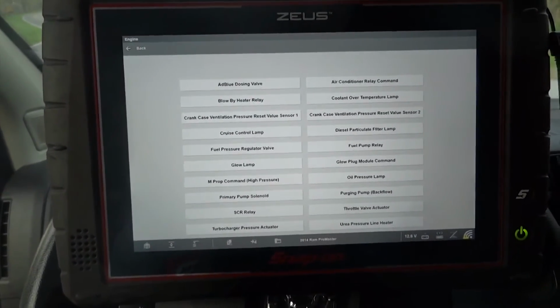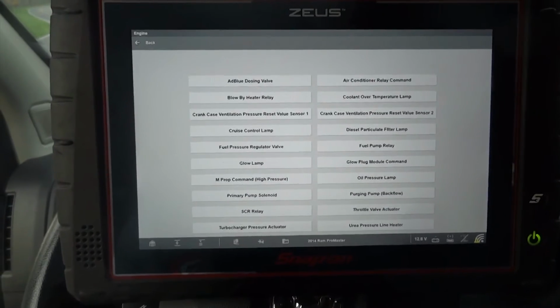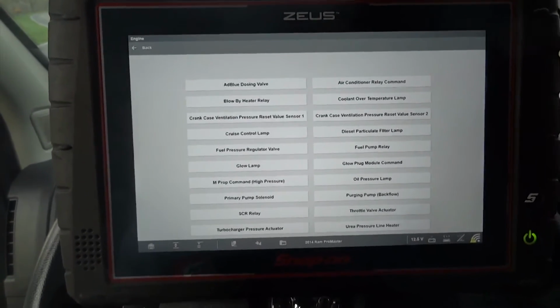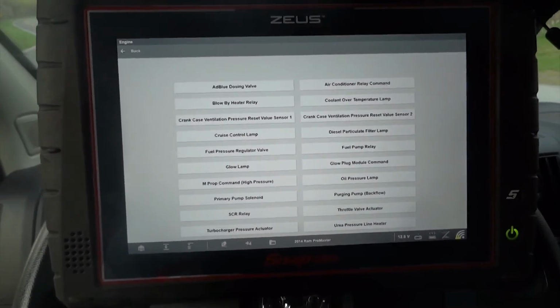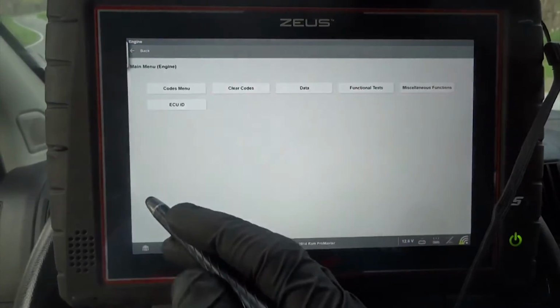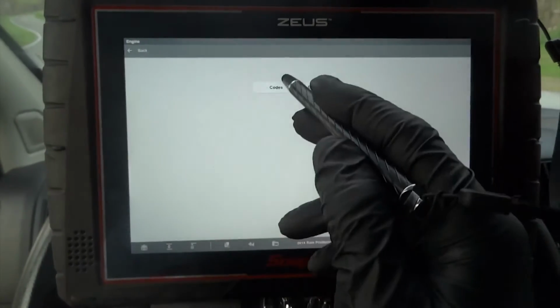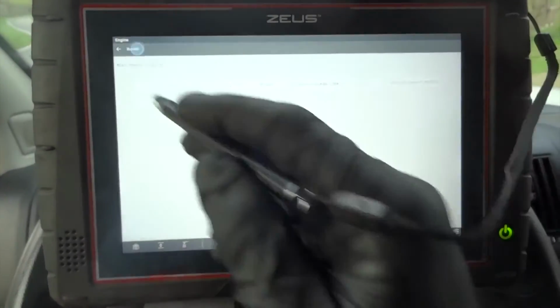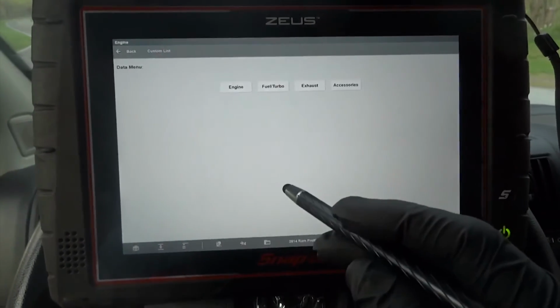Then I'm gonna focus towards the mass airflow sensor. We're gonna check the mass airflow sensor wiring. We're gonna look around the inlet tube to see if we have any leaks. Now let's drive back to the shop. Okay, so we shouldn't have any codes right now. So let's drive back to the shop.